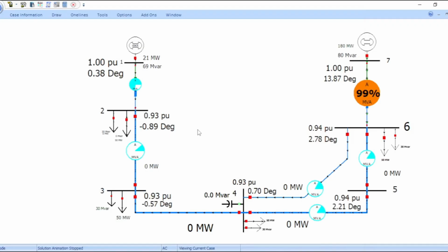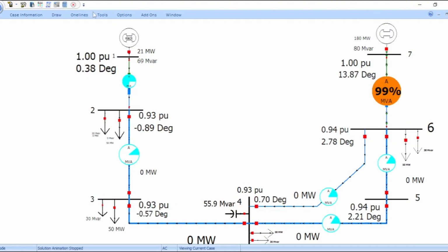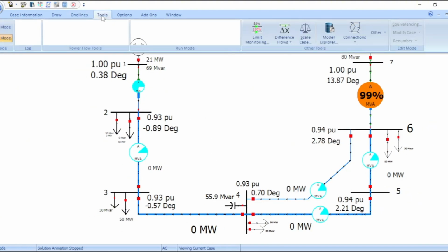Hello, Assalamu alaikum. I'm Muhammad Abdul Saleh Lazim. I'm going to take you through the verification of our method to increase the voltage at bus 4 by 5%. So I have already added the shunt capacitor. All I have to do is enable, or turn on, the circuit breaker here. Then we will go to run.